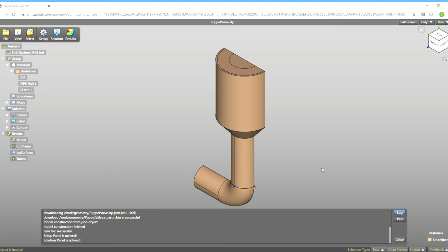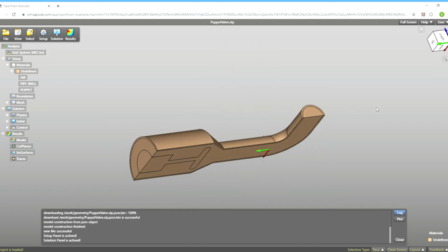Alright, let's start this journey. First, we want to apply boundary condition. Pick the inlet surface. Right-click, Edit. Select Velocity Inlet. Set speed with 4 meters per second. We provide a default boundary condition name. Apparently, we can rename it with inlet. Apply it, then outlet.